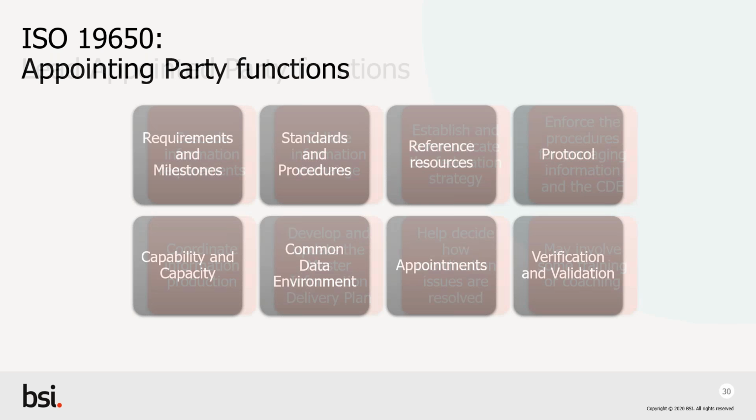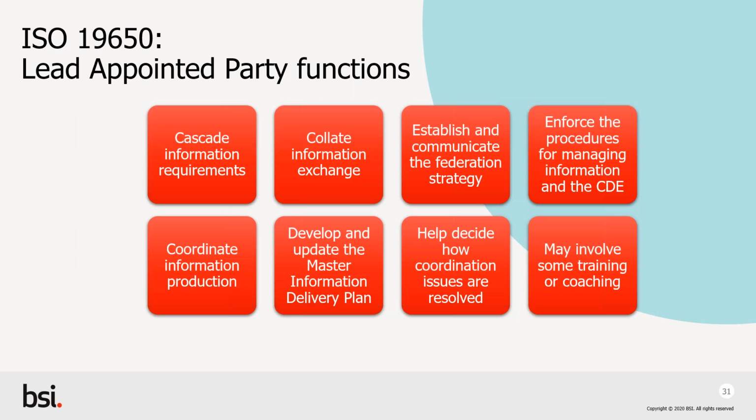Then think about lead appointed party functions. Typically in the Indian environment, this might be the EPC contractor, who takes over the design and drives the engineering, procurement and construction. They have certain functions, and therefore they need certain skill sets in their business as well. You can see some of the functions, but again, I recommend that you read through the ISO 19650 standards, which articulate this in detail, and if required, go through the training programs as well.